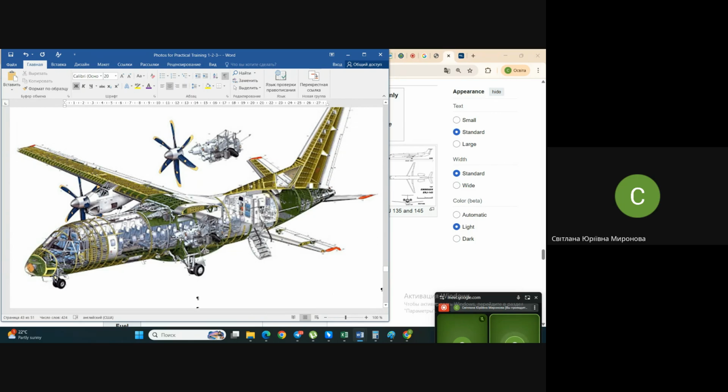So engines are up to you, but forgive me, when you are placing the engines, don't forget that placing engines on the fuselage increases the length of the fuselage, because besides joining the stabilizer and the fin here, you also need to have inner structure to join pylons of engines between each other, because you have a couple of engines, for instance, here, or even four engines.